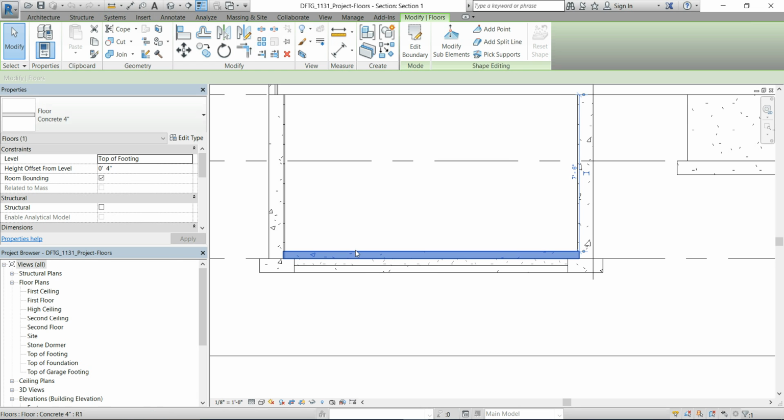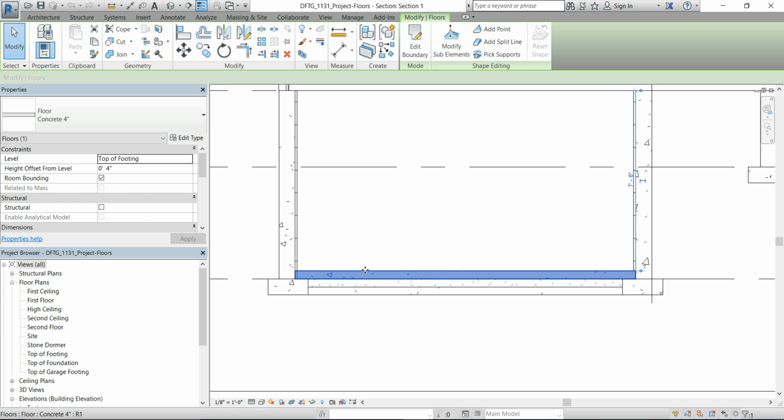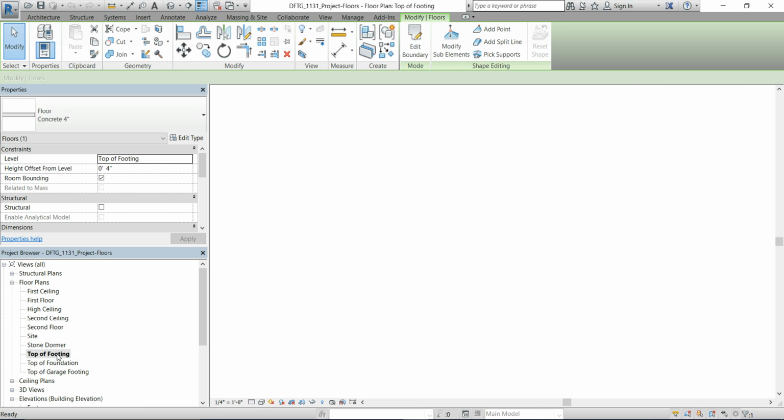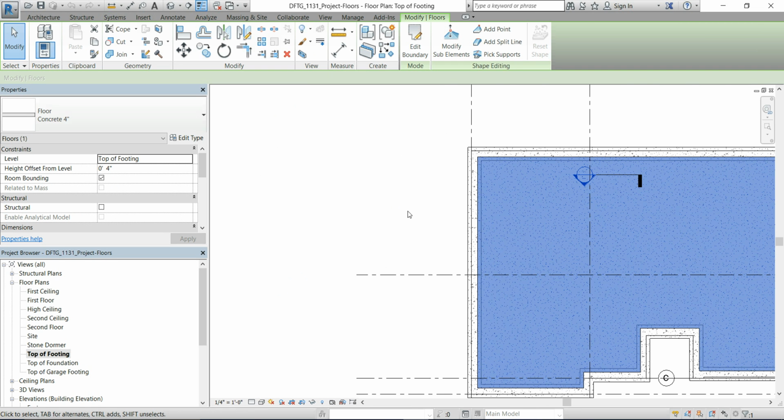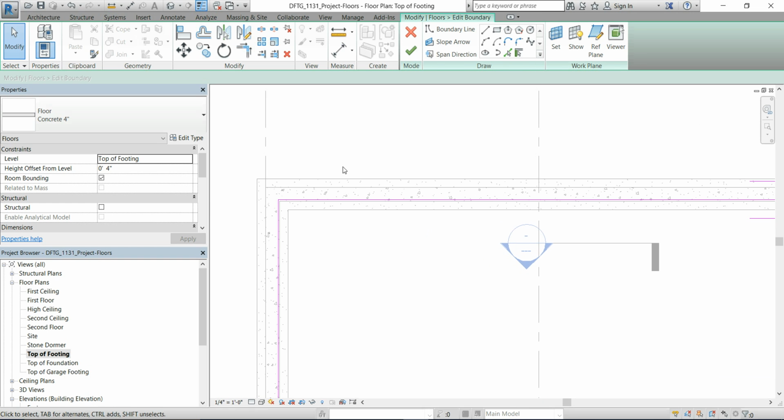When you do your concrete floor, you need a 4-inch offset, and you want to pick the walls, but you want to extend it into the core of the wall, okay, because we've got this 1-inch layer of insulation. So when you go through picking, you can use pick walls on this one, but you want to be sure and check extend into core.